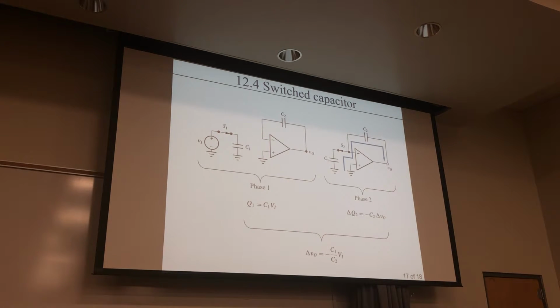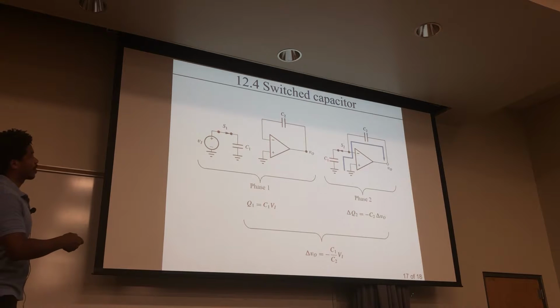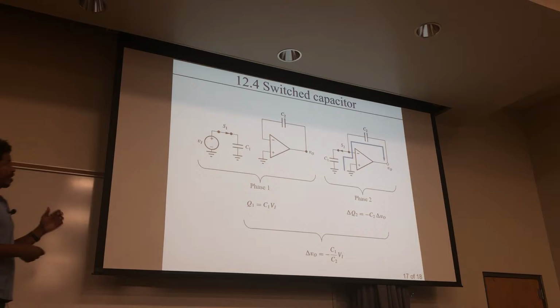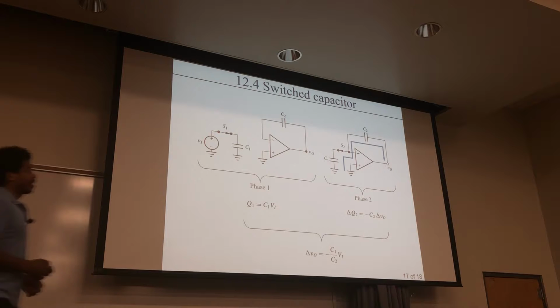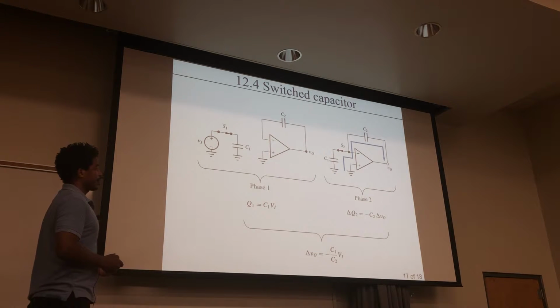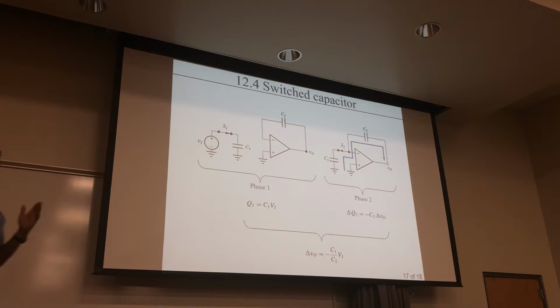So at each step in time, your charge that's being built up on this capacitor is then being passed through, and so you're seeing this voltage that's being changed in time. Okay, so it's just indicating that it's not like instantaneous from 0 to V out. Oh, okay. And it's best to think of it as like you're sampling in time, right?